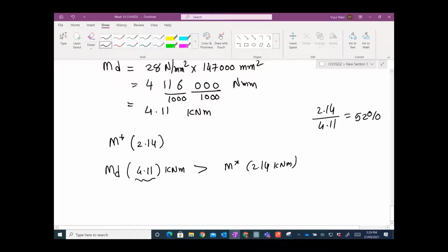So if I come across those capacity factors, I would still be on the safe side if I do not reach a 52% penalty. So if you do the timber examples in the exam and someone says it's quite hard, no, it's not hard. If you don't know your K1 to K12, you can still tell your engineers whether it's going to work or not. Of course, it's not full, but at least you have a picture. Within less than 1 minute, you can tell by looking at the beam whether it is going to fail or not. As I mentioned, it's conservative. You don't take into account K1, K4, K9, K12, but at least you know that the beam is going to work. Okay, so that is just a quick overview.